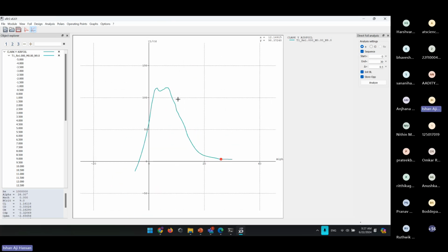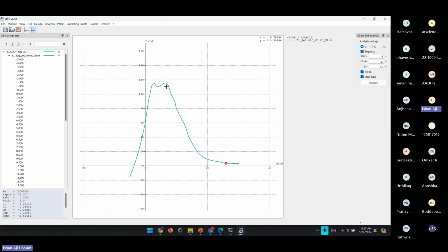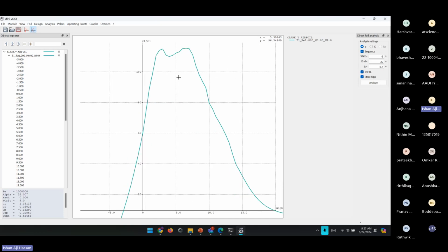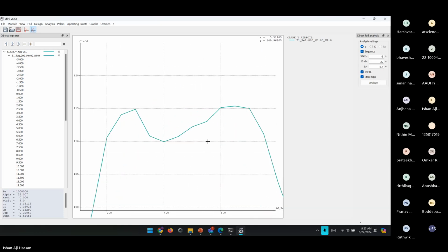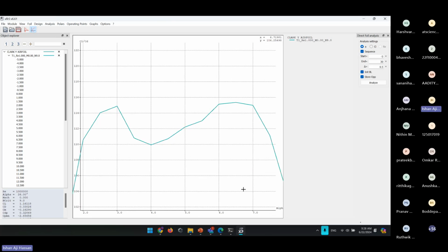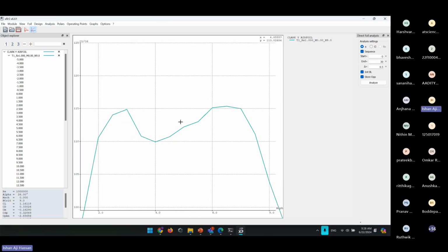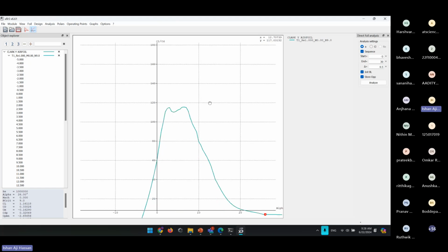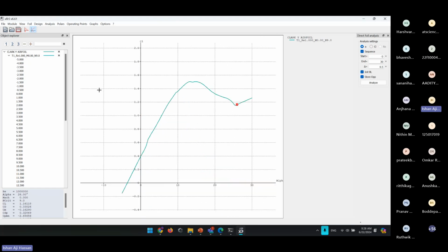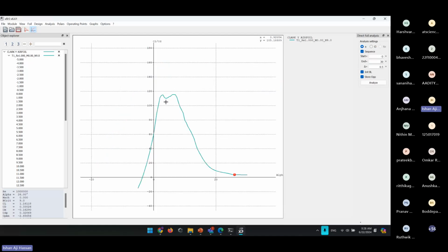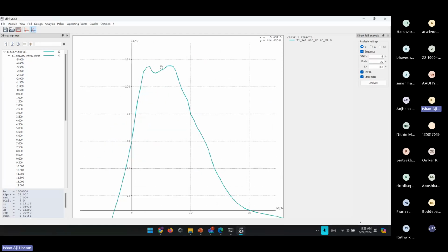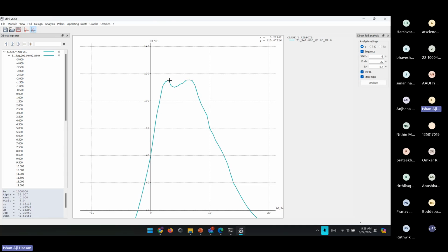Here for this graph, we can see that the peak of the CL by CD curve is, if you zoom in, around 3 degrees to 7 degrees. That is the peak of efficiency of this airfoil. But as we have seen, CL increases all the way up to 14 degrees. This doesn't mean that if the peak of the CL by CD is here, the highest possible lift you can generate is close to this angle. It just means that the most efficient flight is at 3 to 7 degrees.